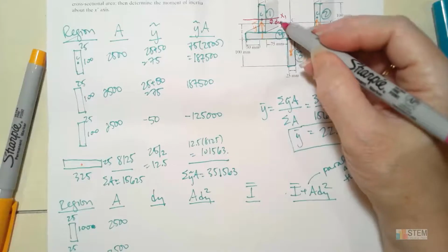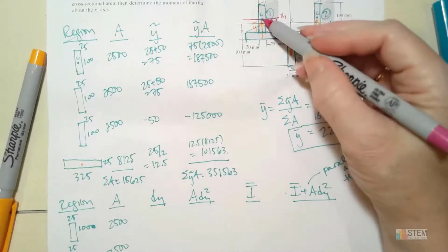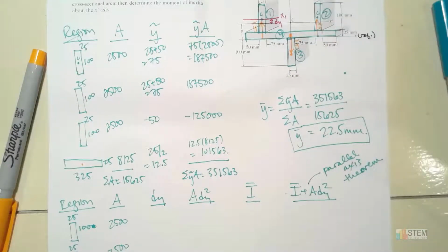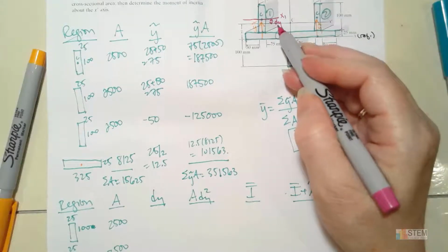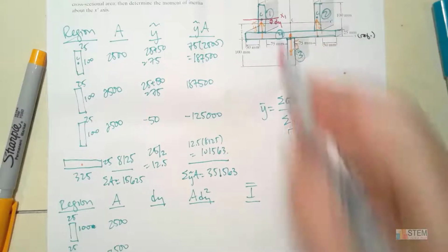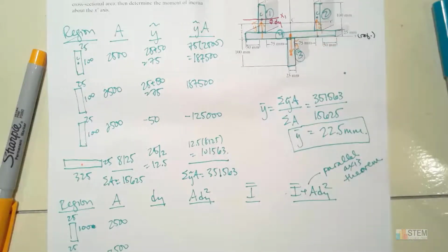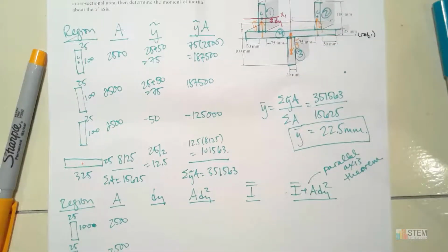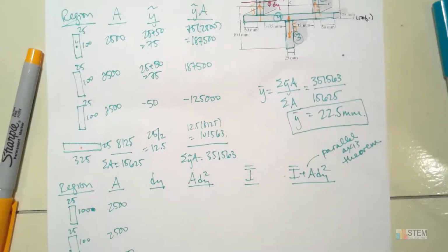So that takes care of the fact that the centroidal axes don't line up in this problem. So that's what dy will be. All right, it's just the difference in location between those two axes. And we're doing a vertical distance because we want to take the moment about a horizontal axis. All right, so that distance has got to be in that y direction.